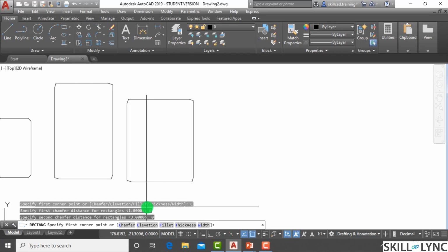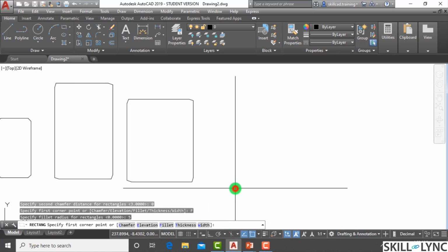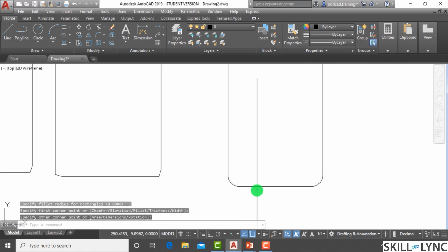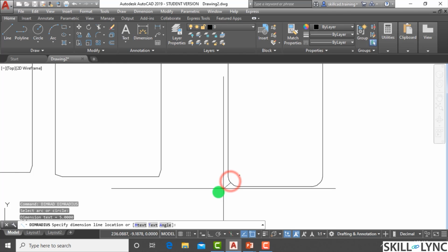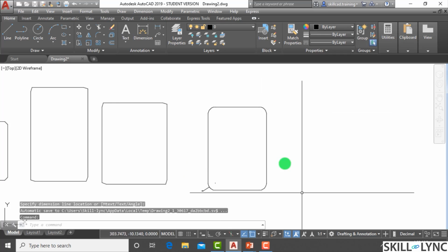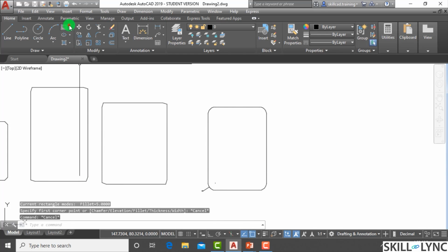So now I have another option called fillet option. So what does fillet option do? So here it says specify fillet radius. So you give a fillet radius of 5, and if you click on it and create a rectangle, you see that. So I take a radius and see that the corners are filleted with 5 units of curve over here. So it is throughout.